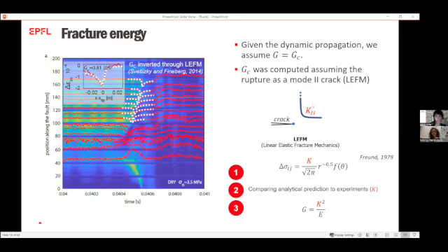So this stress intensity factor determines the severity of the stress perturbation. So we followed, as I just said, the protocol from Svetlizky and Feinberg. As a first step, we defined the shear stress perturbation expected by the theory, by linear elastic fracture mechanics.